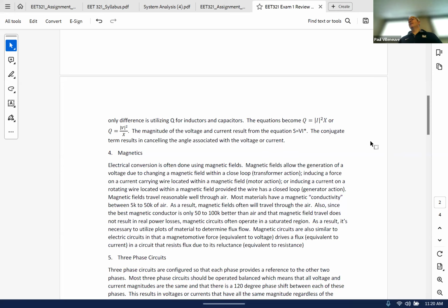It's up or down. Your power triangle tells you the direction, right? So when you do your phasor diagram, if current is lagging or leading, you can draw your power triangle, and then you just stuff in your value of Q, and then you know if it's up or down based on the power triangle you drew. So you don't keep the negative or the positive. That has to be drawn based on the power triangle.